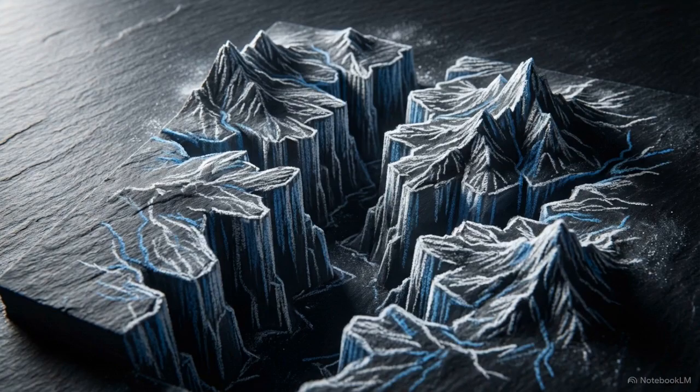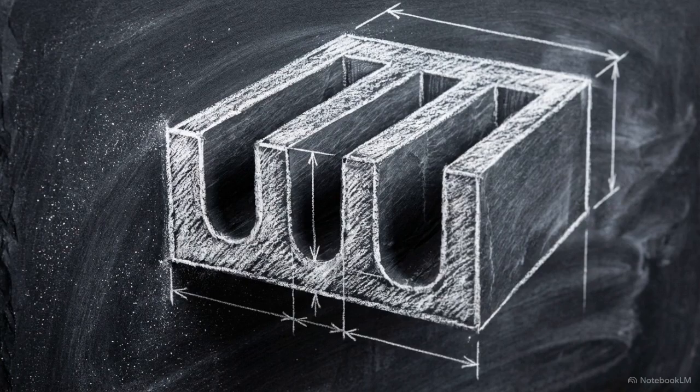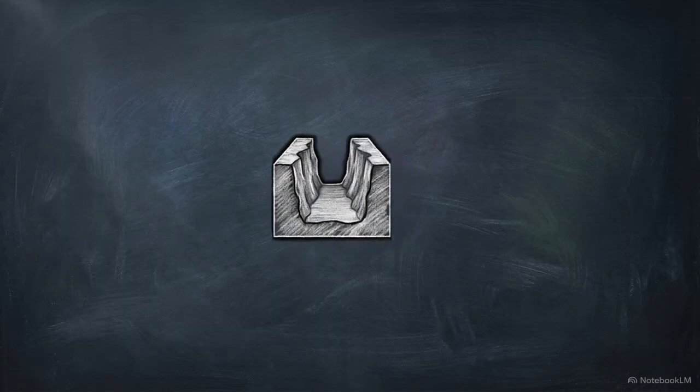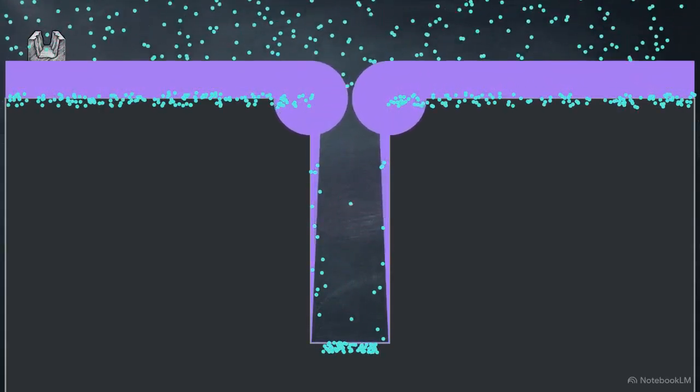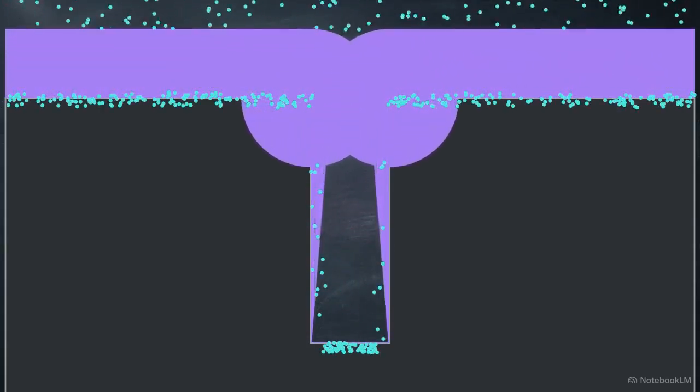The second major limitation of conventional CVD is spatial. Modern microchips feature high aspect ratio structures, which are deep, narrow, microscopic trenches etched into the silicon. This animation shows the physical failure state of continuous vapor flow in these narrow geometries. As precursor particles enter from above, they rapidly build up thick layers at the top corners, eventually merging to seal shut an empty void in the lower half.